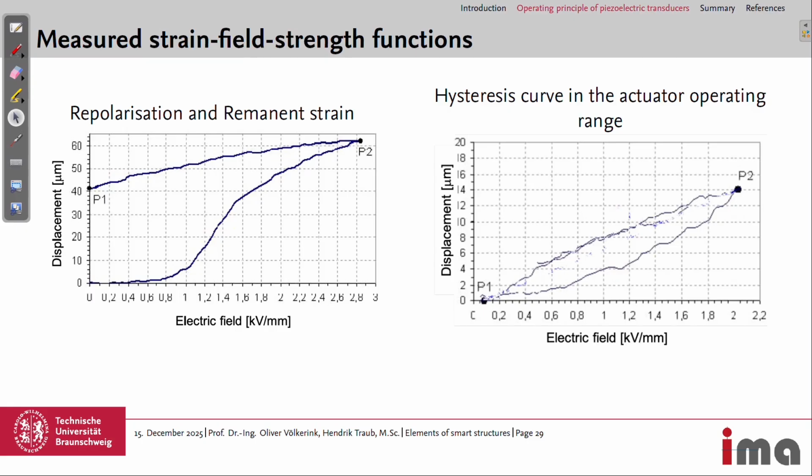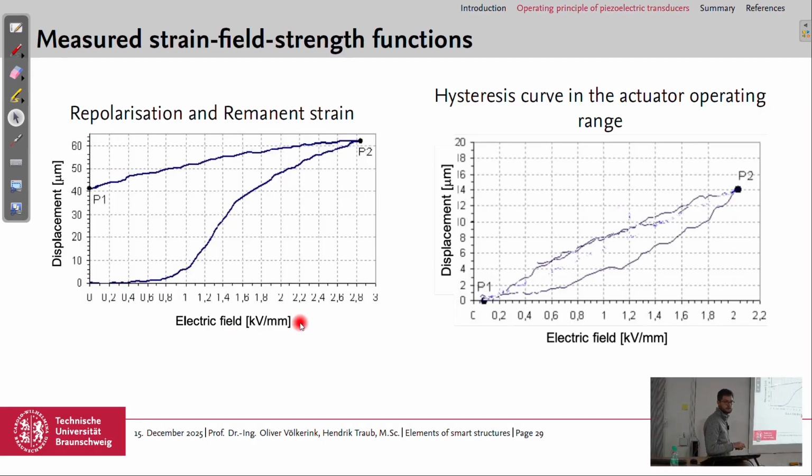Further questions? You have mentioned that we require at least 2 kilovolts per mm for the polarization. Doesn't it depend upon the thickness of the material also? Yeah, sure. If the electrodes are further away, then you need a higher voltage. This quantity is specific to the thickness, so you multiply it with the thickness of your material, and then you get the voltage you need.